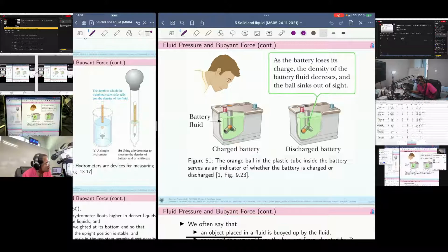They drill this hole open and leave this part open so that the owner of the car or anybody could look at this hole. When you observe the ball from this hole, and if you could see it, it means that the battery is in good condition.